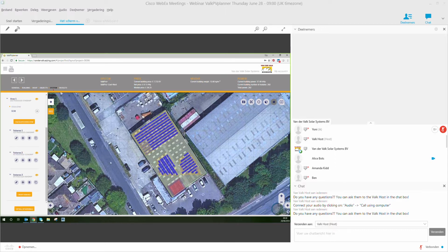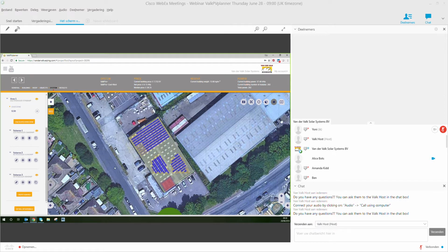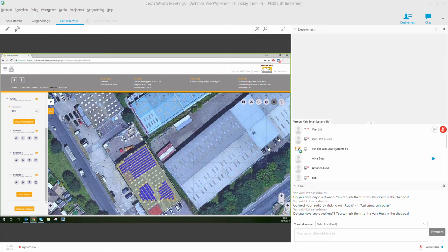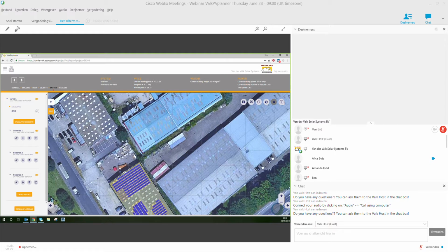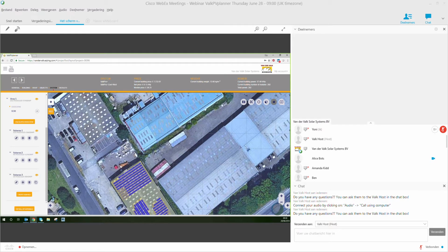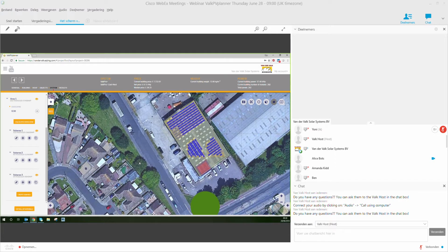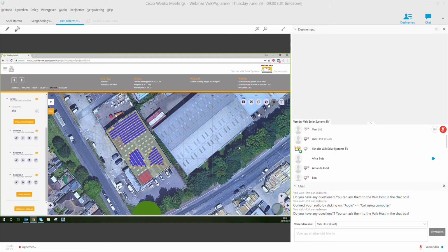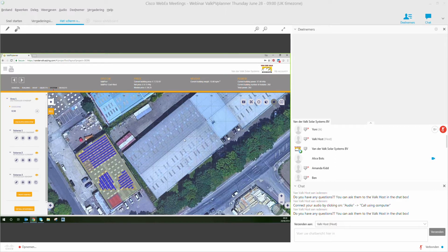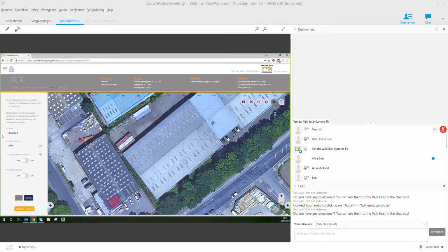Okay, if you want to add a second building, whether that's this building here or any one of these buildings, in fact, you do that here on the plus sign. What I'm going to do is take the opportunity to show you a pitched roof. Let's do a commercial trapezoidal roof. So we'll say this one here, let's say this is a pitched roof. So we're going to add a new building here, building 2. This one might be trap roof. Maybe it's just 4 meters high. 25 is the maximum height you can design up to in the software.